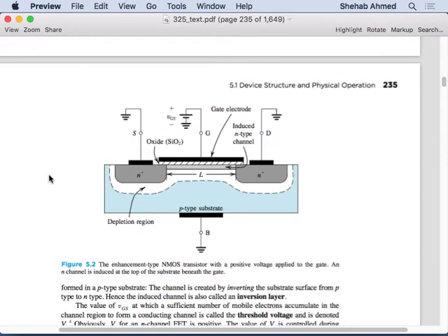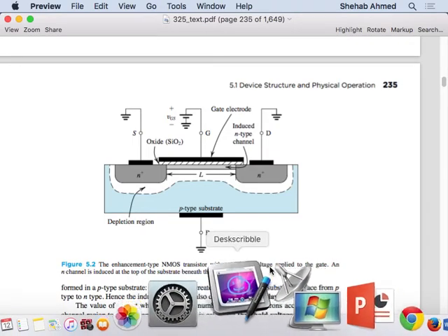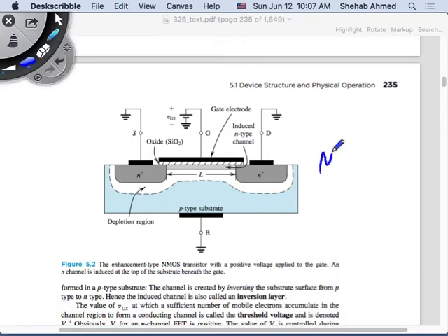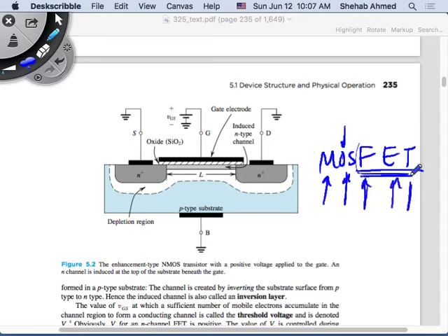So, just before we move on, do you see now where the name field effect transistor comes from? So, metal oxide semiconductor. Field effect is due to these electric fields that I'm applying that are the reason to cause the current to flow. So it's this external field, due to the voltage applied between the drain and the source, or the drain and ground, because source is at ground potential, for example, in this case.